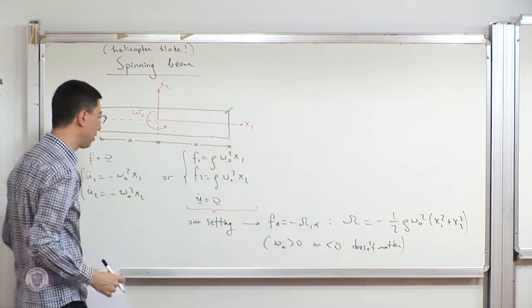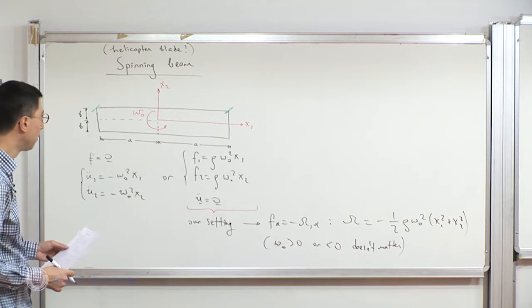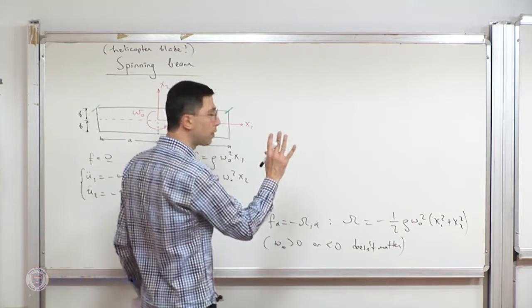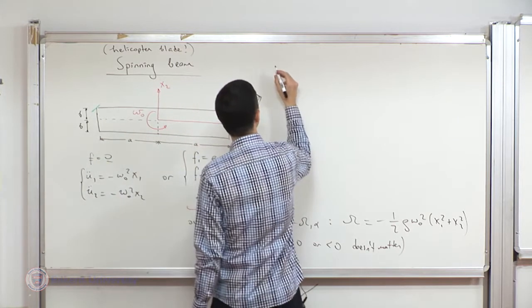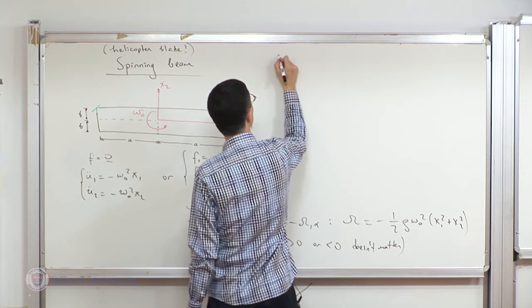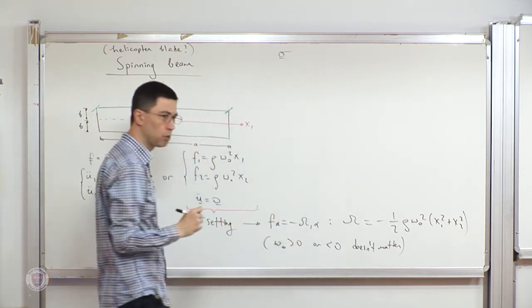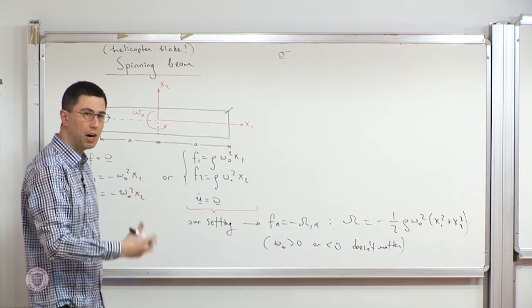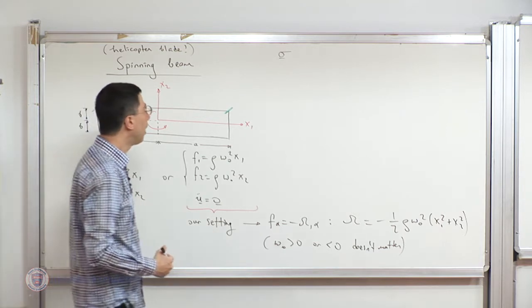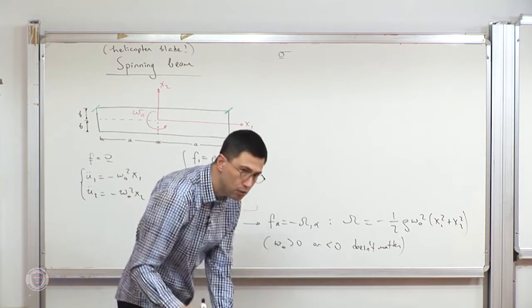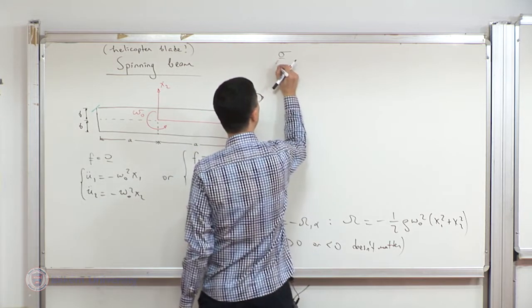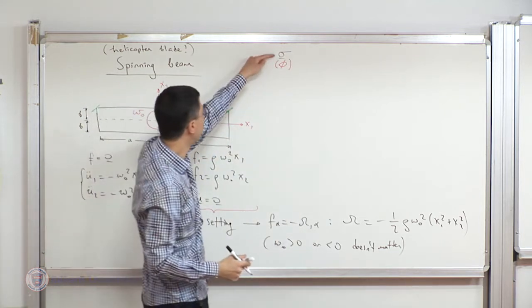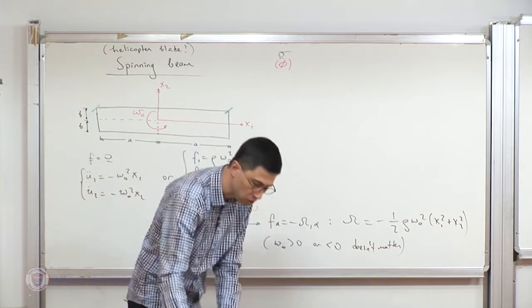Although I've drawn the direction of rotation according to the right-hand rule. Okay, so now what we're going to do, remember, is that we are going to start with the solution diagram for the stress-based approach: you propose a form for the stress field that a priori satisfies equilibrium. And we're not going to do it directly in terms of sigma. Now we know that what we really propose is not sigma, but rather an Airy stress function. So the stress is derivable from the Airy stress function.